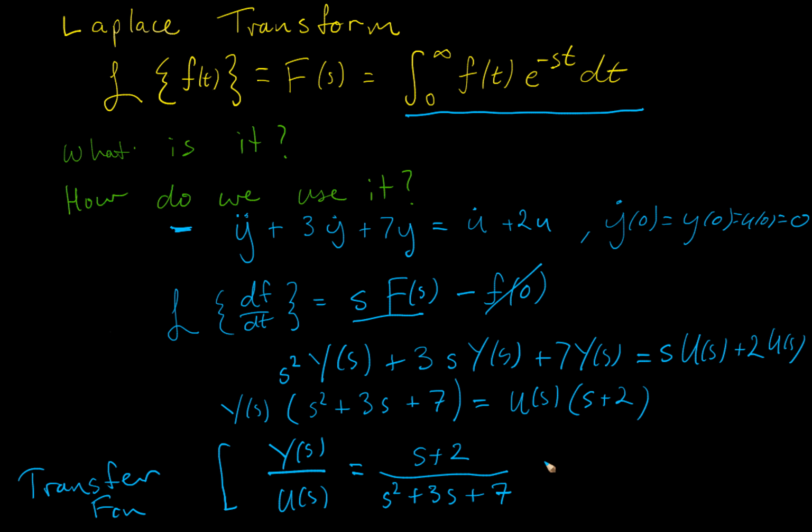And often we're going to use symbols like G(s) for that, or it might be C(s) or H(s). G(s) is often used for the system dynamics, K(s) for a controller. So the transfer function tells us that if I've got some input in the Laplace domain, U(s), and I want to know what the output is, I just multiply it by G(s). And G(s) is this rational function.